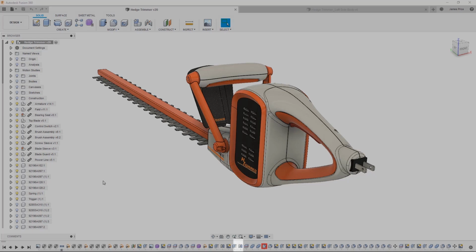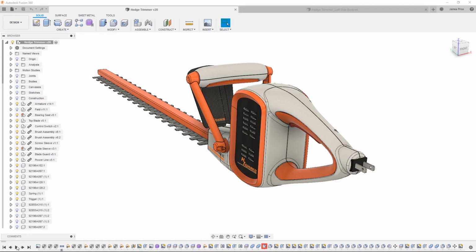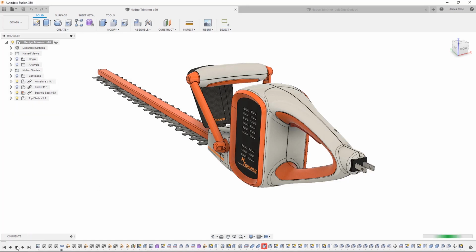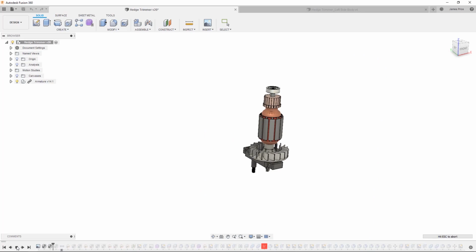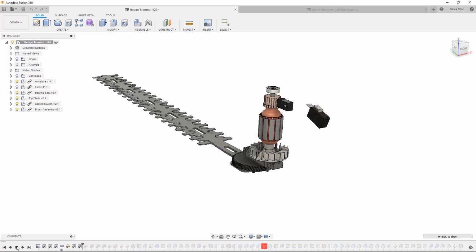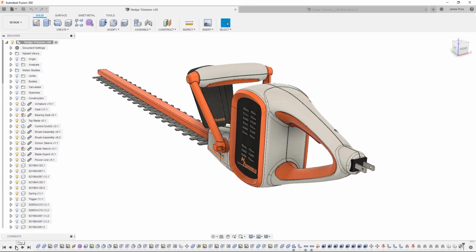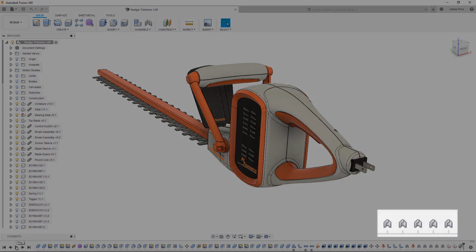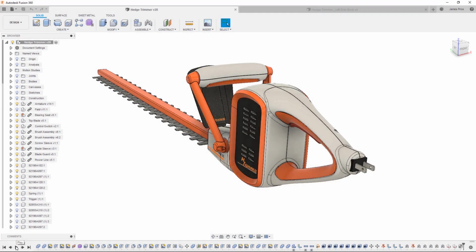Finally, the timeline is similar to the feature manager tree in SOLIDWORKS, but instead of being on the left side of the screen, it is on the bottom. It is similar in that features are captured in time, they can be edited, reordered, and deleted, which will update downstream features parametrically. One major difference is that you will notice that joints, or what we call mates from SOLIDWORKS, are also captured parametrically in time. This is like combining your part and assembly environment into one design, which can create some more robust workflows, which we will discuss in a future lesson.